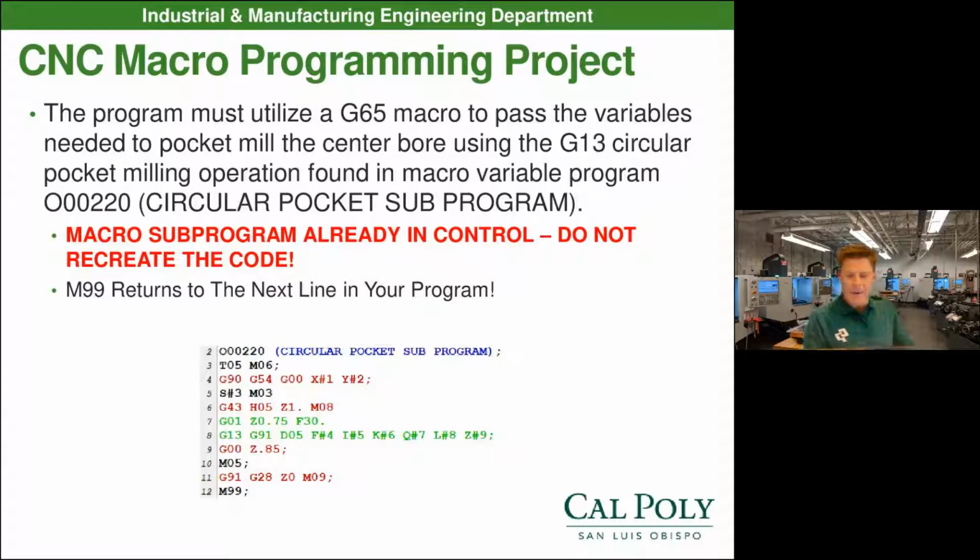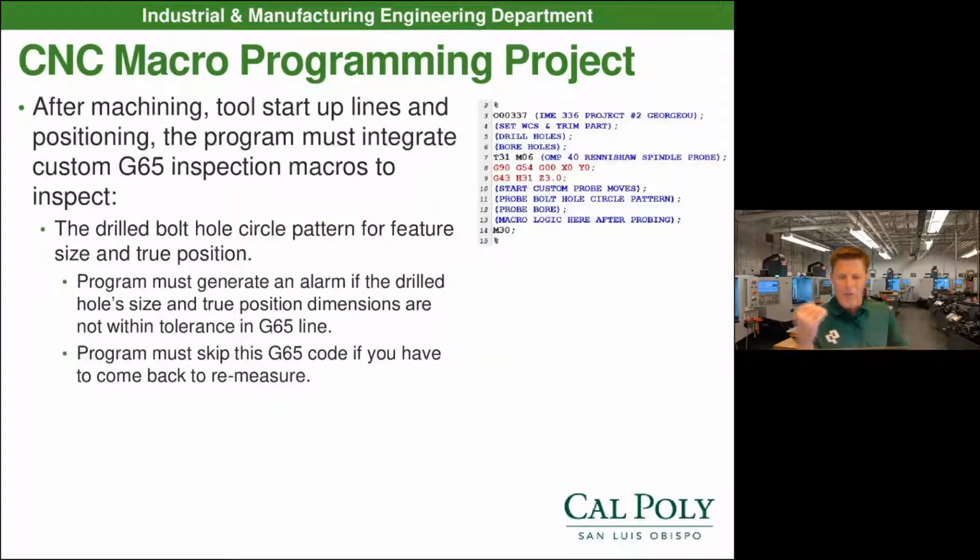So they send those variables to the control and hopefully mill the correct size pocket. The thing is, they think they have a 5/8 tool. Treon gave them a sharpened tool. They had no clue. So then when they run that sharpened tool, their bore size is going to be oversized. Or undersized, sorry.